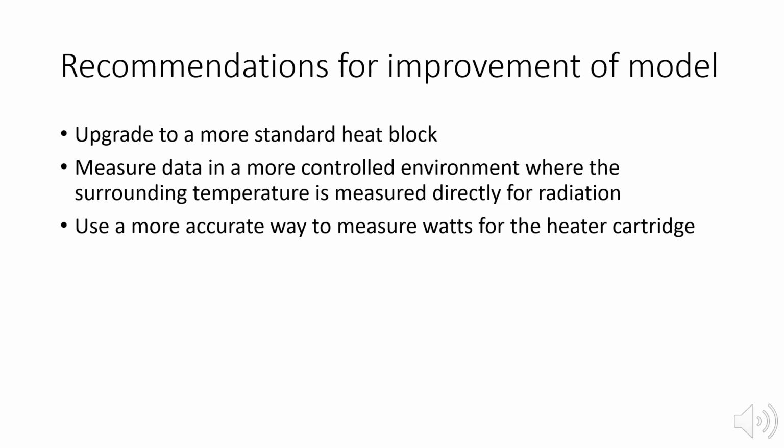To improve on this model, the first thing that should be done is upgrading the heat block to a more standard heat block that will allow for more heat transfer. By doing this, we can have more confidence that all of the energy being measured by the watt meter is going into the heat block.